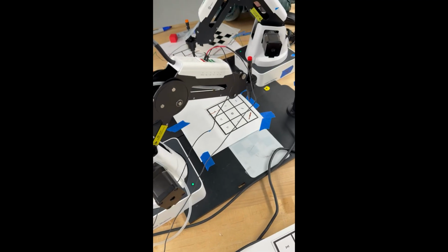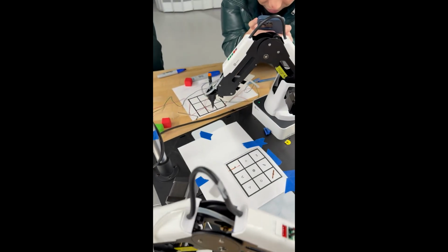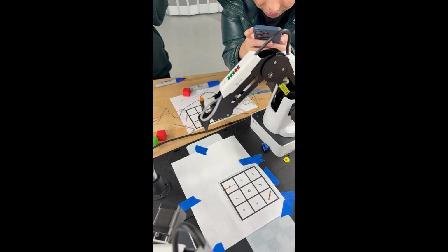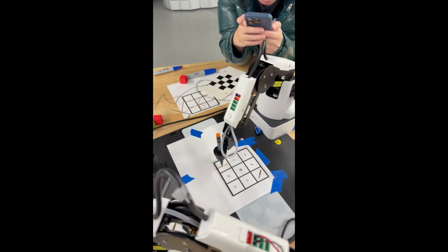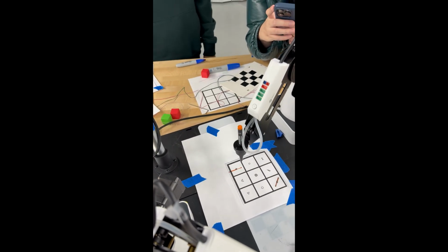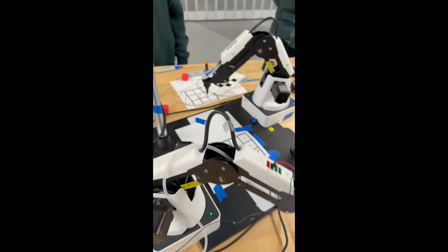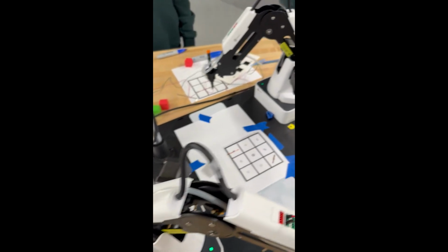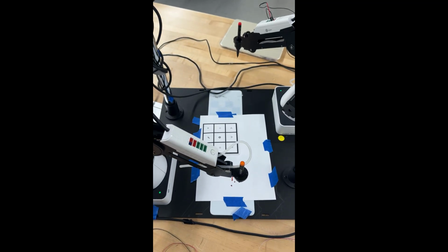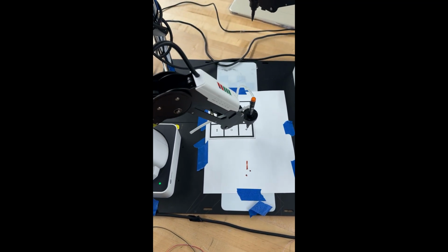After this, the team added a shell module to code in some movements that the robot would do within the chosen square. We used the world points from the calibration file as inputs and added different values each to the x and y and used the result as an output. This output would, when used in the following move point blocks, cause the robot to create diagonal lines starting from the center of the square.